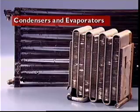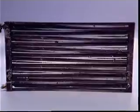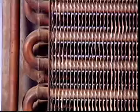This section examines air conditioning condensers and evaporators. The function of the condenser is to transfer heat from the high-pressure, high-temperature refrigerant to the outside air. In light vehicle applications, it is normally positioned in front of the radiator, where it is exposed to maximum ram airflow when the vehicle is in motion. The airflow is assisted by the engine cooling fan or by an auxiliary electric fan, and these must create sufficient airflow when the vehicle is stationary.